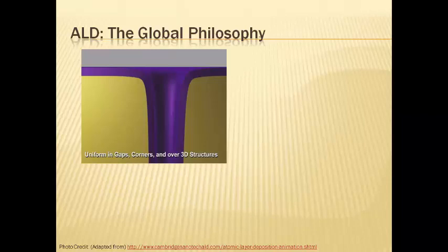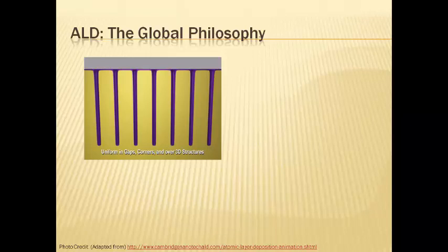Thus, each capacitor trench now looks like this, a conformal coating of aluminium oxide with precise control over the thickness. And a zoomed out view shows the array of DRAM capacitor trenches in all its royal glory. Note the aspect ratio. It's roughly 15 to 1, greater than 10 to 1, as Professor rightly claimed in one